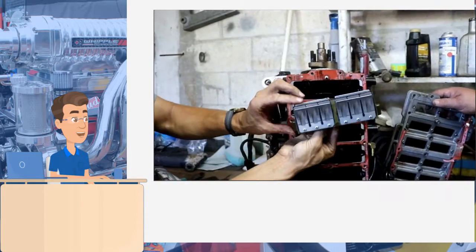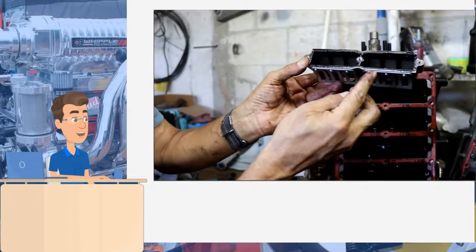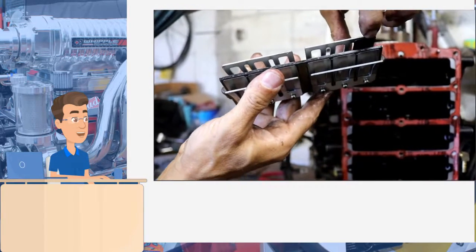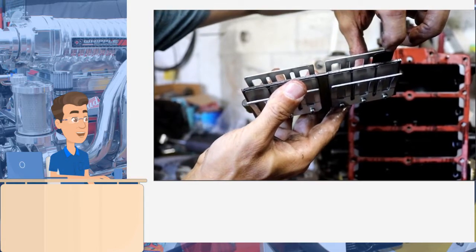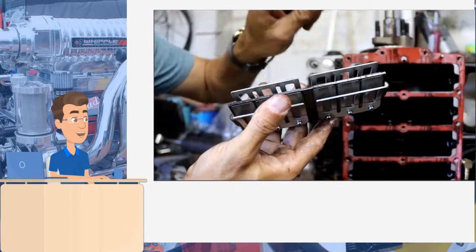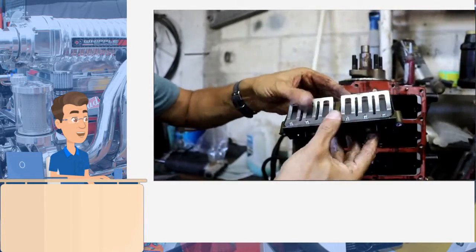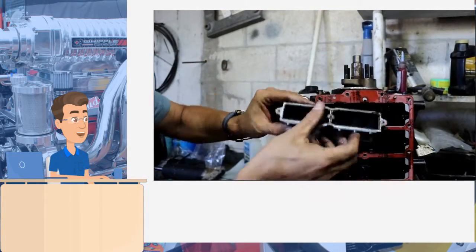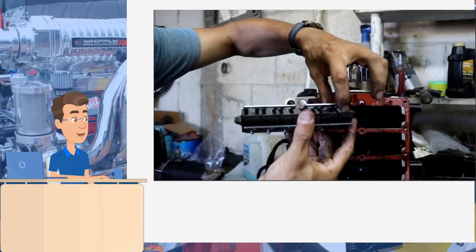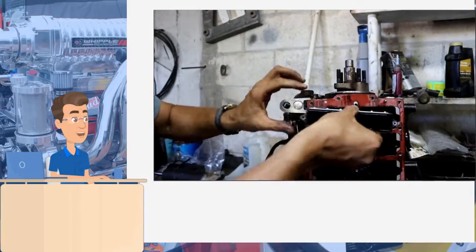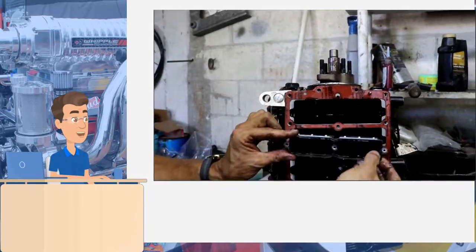And the reed valves are located over there, one group of reed valves like this per each cylinder, per each piston. They allow the air in one direction, and the air enters over there, and in the other direction, they close and avoid the movement in the opposite direction.